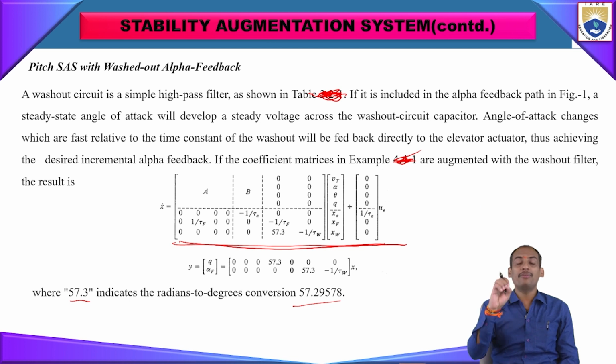It is beneficial when we are checking how the control surface will behave for different types of inputs, for higher inputs, for lower inputs, for a negative moment, for a positive moment, for a negative rolling moment or positive rolling moment. How these control surfaces are affecting the stability of the aircraft.